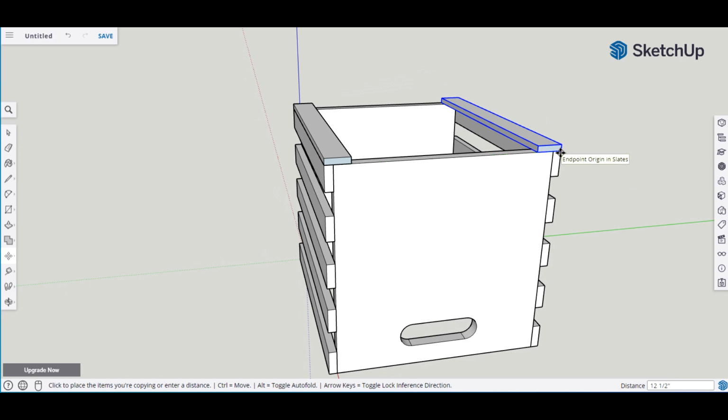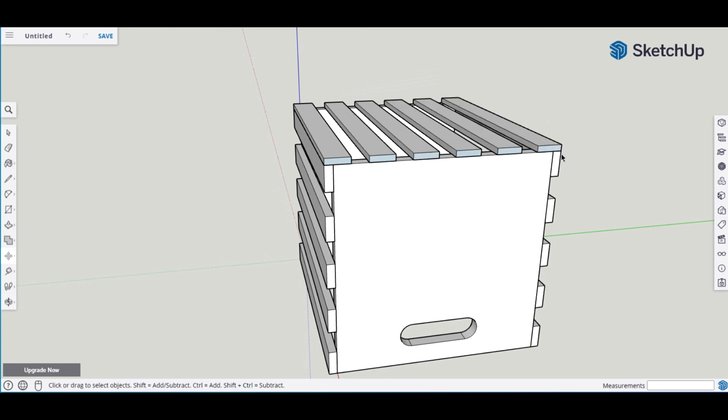In other words, press the mouse key once, slash, bottom right, and then let's do 5. That should give us 6 slats across the bottom. Boom, let's count. Space bar, 1, 2, 3, 4, 5, 6. There we go. So it's how many additional you want, including the one that you moved, and then it'll add this to it. So a total of 6. I selected /5, which gave me 5, plus 1 gives you 6. There you have your completed crate.